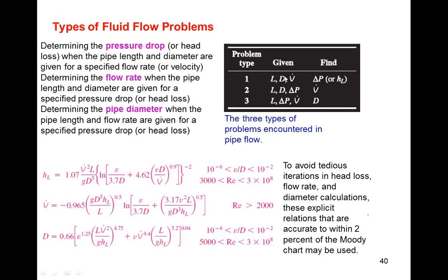Hello. Yes, sir. So this is the prime consideration. You should maintain a particular vapor pressure in the pipeline to avoid vaporization. Vaporization creates cavitation in the pipeline. And sometimes you might have seen that your pump is continuously running and water is not coming out from the pump.